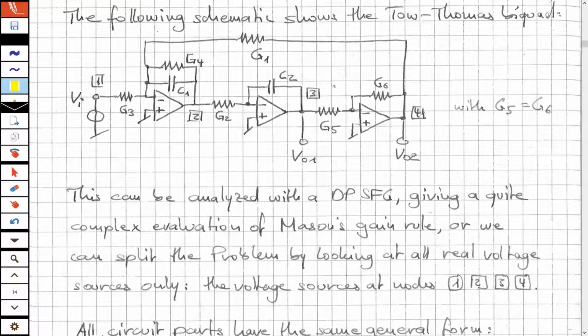The main difference to the circuit before is that this here is now an additional circuit. So why do we need an additional circuit? The reason is that with an operational amplifier, it is not possible to build a positive integrator. You can only ever build inverting integrators. So 1 over SC is not possible. It is minus 1 over SC which is possible. And if you have two of them and then the feedback, it will have the incorrect sign.